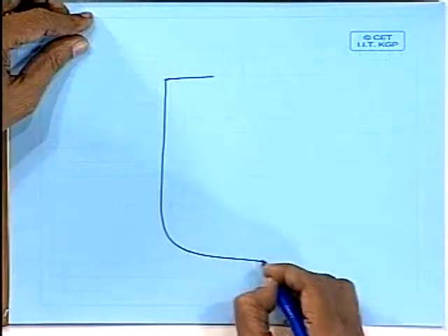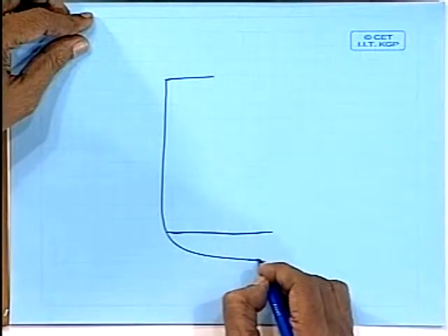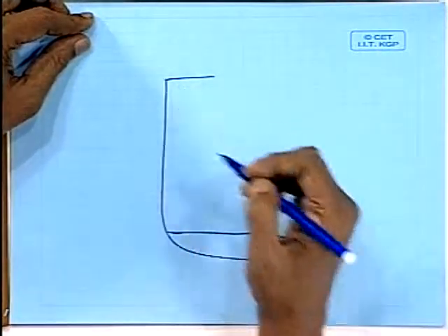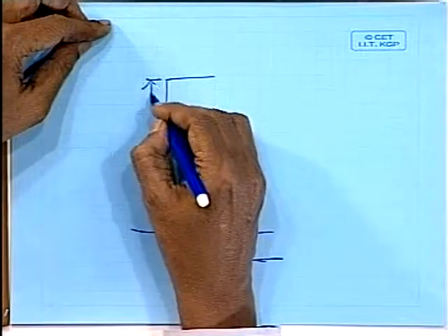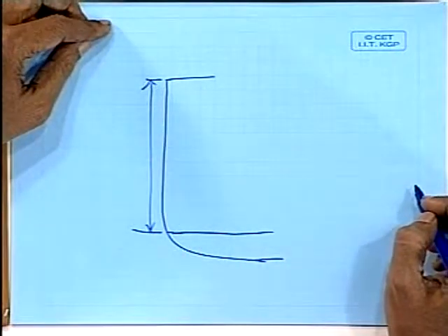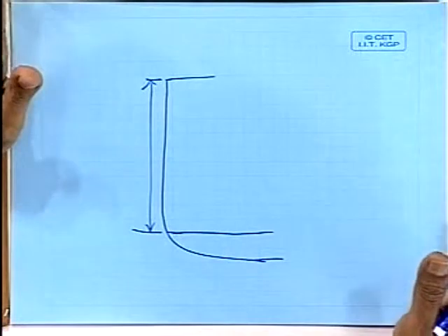Am I clear? So what is a primary support? When you are talking about the main shell plating, stiffening of the main shell plating, the primary members are the shell plating itself, the keel plate, the double bottom plating and the deck platings. Now suppose I have got a single deck ship, only a single deck is there, and I want to frame it transversely. You can see the span of the frame will become so much, and as you can well imagine, it's very high.